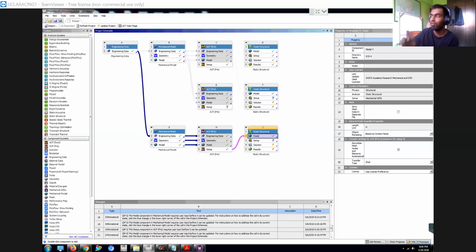Remember last time we had the side panels at a thickness of 6 plies, whereas the center panel was 3 plies. Because of the difference in thicknesses, ANSYS was not able to produce a shell model. That's my bad, I forgot about that. If you want a shell model, you have to make sure the thickness throughout the entire part is uniform. If not, you have to use a solid model, which is not much of a big deal, more or less the same thing.